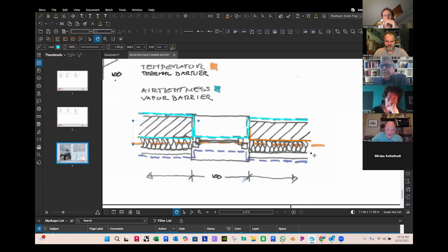So we have an inner layer, the gypsum board, then the protection against humidity getting into the structure, which is this stick and tape, and then the insulation, which is outside of the inner humidity, and then whatever kind of cladding at the outside to cover the whole thing.